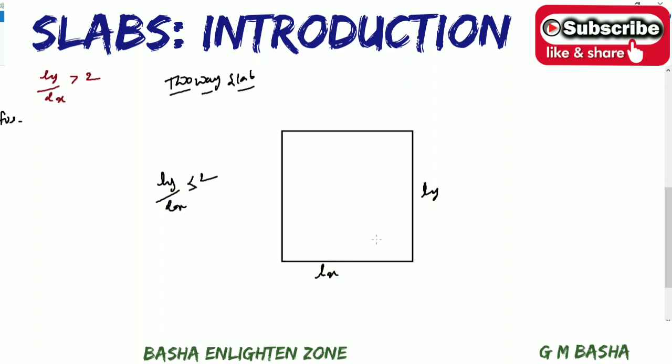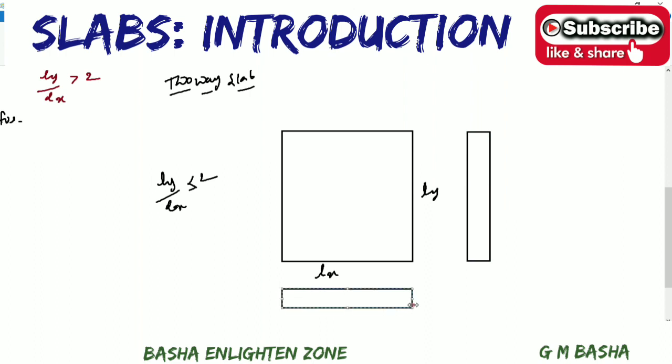These slabs are likely to bend along the two spans, and such slabs are called two-way slabs. Means these two-way slabs will bend in both directions, in the y direction as well as in the x direction. So you will get deformations in both directions. I am roughly indicating the deflection here, like this. It will deflect in both directions.